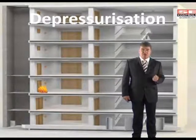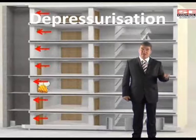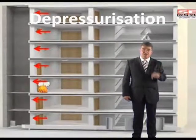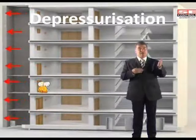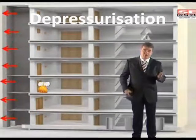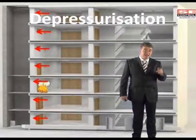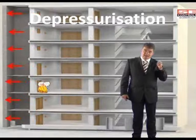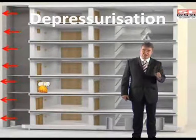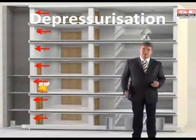Depressurisation is smoke control using pressure differentials in which the air pressure in the space containing the fire is reduced. So rather than make one higher than the area protected, reduce the pressure where the fire is, below that in the adjacent spaces, so it makes the smoke go a certain way. Then gases are removed from the smoke affected space in a way that maintains the desired pressure differences across any leakage openings between that space and adjacent spaces.